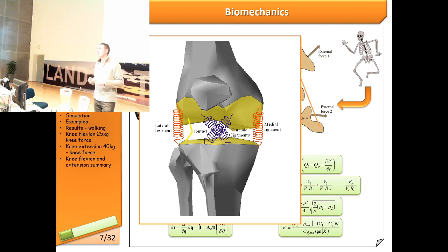You can model a hinge joint using just constraints, or you can have a pin, a contact surface, you can have clearance, depending on how much detail you really need for your simulation, and whether you're caring about the stresses on the pin in the hinge joint, or whether you just need to know the overall force that passes that joint. You will choose one model or another, because it's related to computational cost.